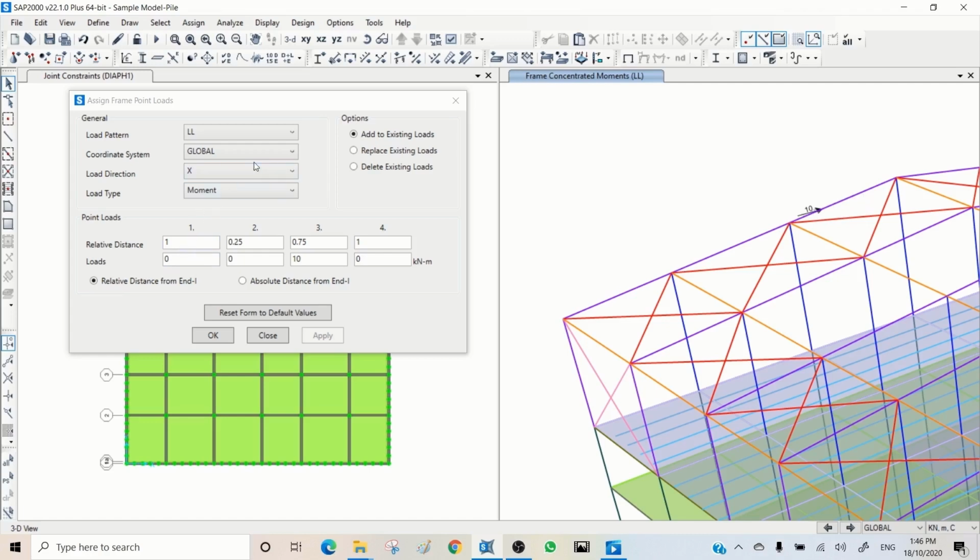So this is how the system works. You can use local, and when you put local, that means it's not exactly on this. If I use the same here now and put it, for example, here, just to compare with X, and add it up to this, you can see this is not aligned with the element, but this is aligned with the element. That means this is aligned with axis 1, but this is aligned with axis X.